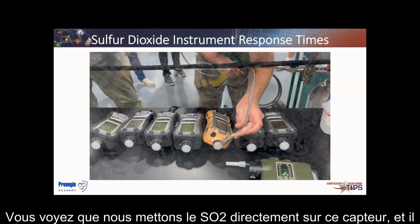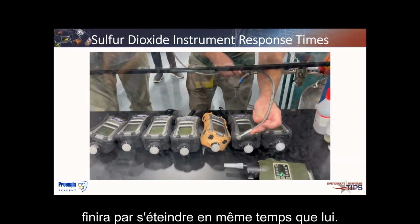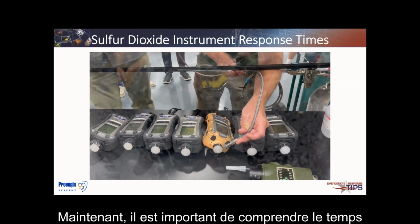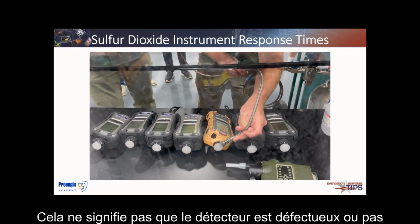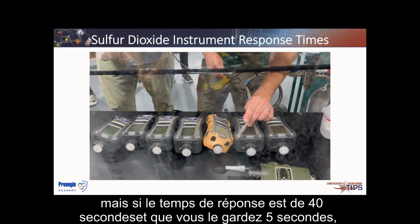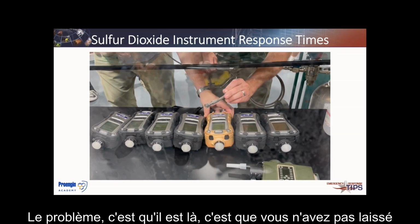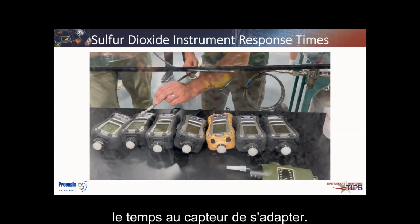So you're seeing we're putting the SO2 directly onto that sensor, and it'll eventually go off. Now, it's important to understand, with every detector you're dealing with, the response time. This doesn't mean that the detector is bad, but if it has a 40-second response time and you're holding it there 5 seconds, you don't see anything, and then you use that to make an indication of what's occurring, the problem is it's there, you just haven't allowed the sensor long enough time to respond.